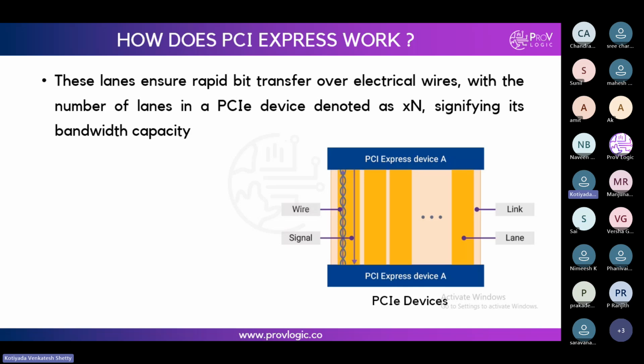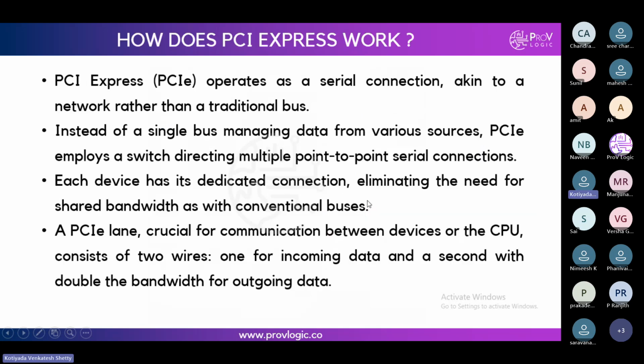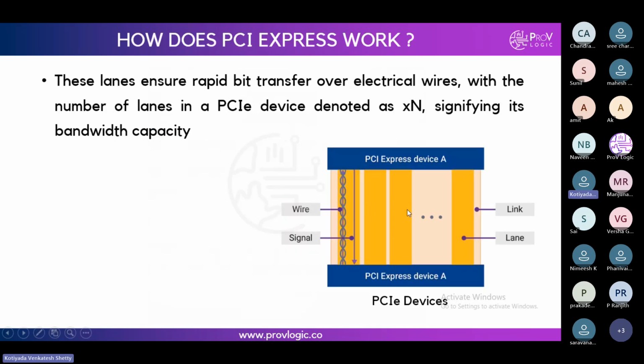If you remember the differential signals from analog, from previously studying in academics, there are differential signals, plus D and minus D. Through the differential signals, nothing but wires, the communication will happen. These blue lines are called the differential signals. Together, the pair of differential signals is called a lane. These yellow highlighted things are the lanes. Together, lanes are called a link.